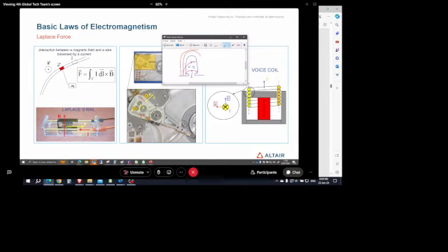If they cannot go out of the slot, let's say if you have wires in touch and they will touch each other, it will degrade the insulation, and at the end you may have accelerated short circuit, a turn short circuit, for instance. So this is something important to have in mind, and this is why we try to fix the wires in the slots as much as possible.